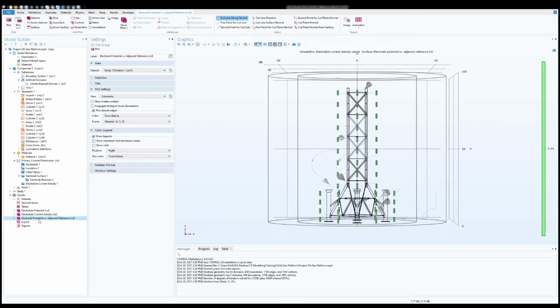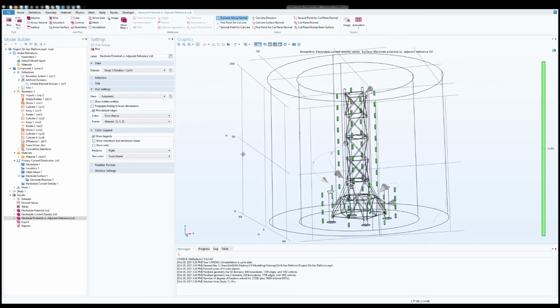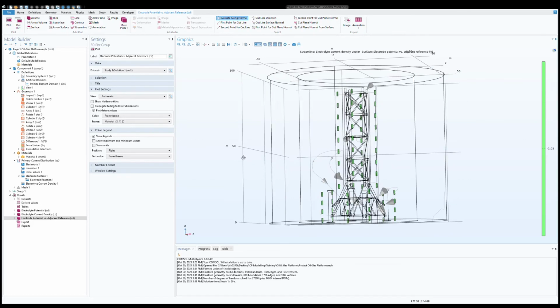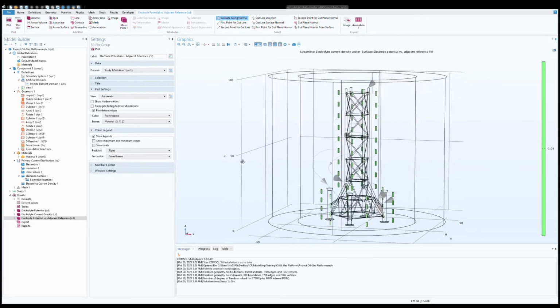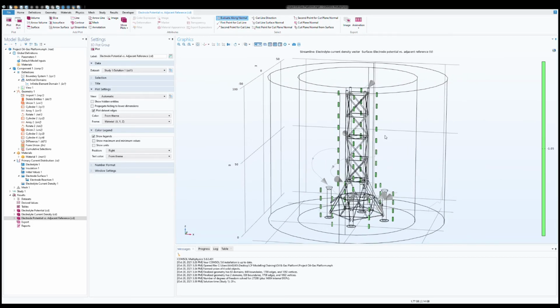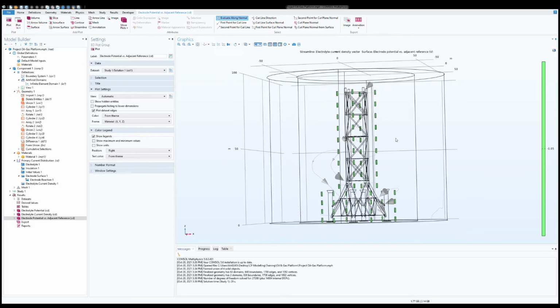The third tab is electrode potential, basically anode potentials, as we have chosen aluminum anode. We can see all the anodes are active and exhibiting 1050 millivolts. The unit is now shown here, minus 1.05 volts exhibited by the anodes.